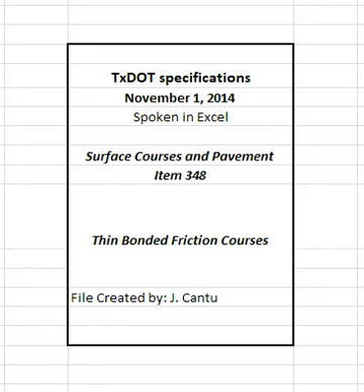4.7.3.1.3 Thermal camera. Take immediate corrective action to eliminate recurring moderate thermal segregation when a handheld thermal camera is used. Provide the engineer with the thermal profile of every sublot within 1 working day of the completion of each lot. Report the results of each thermal profile in accordance with Section 348.4.2, Reporting and Responsibilities. The engineer will use a handheld thermal camera to obtain a thermal profile at least once per project.